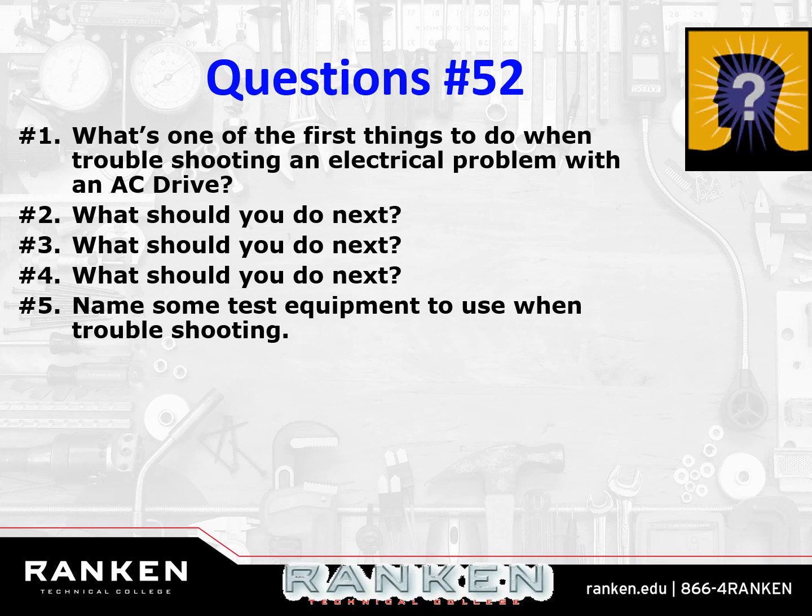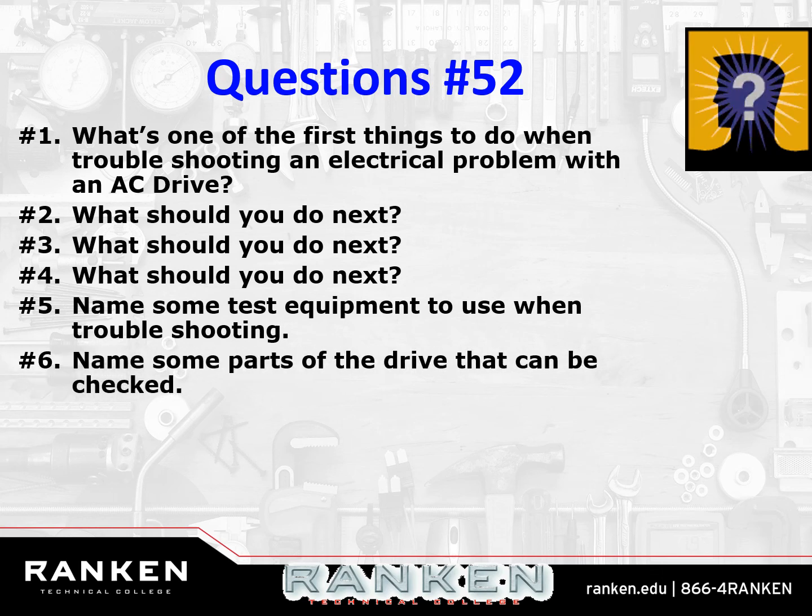Name some of the testing equipment to use when troubleshooting. Well, voltmeters, ohm meters, amp meters. Those are three pretty good ones. You can use a megohmmeter if you would like. You can use a diode checker if you would like, if you want to go that far. Most of the time, you don't need anything more than your fluke meter, your volt-ohm meter. Check voltage and check continuity. Make sure nothing's shorted out. And if there is, you fix it. If not, then move on.